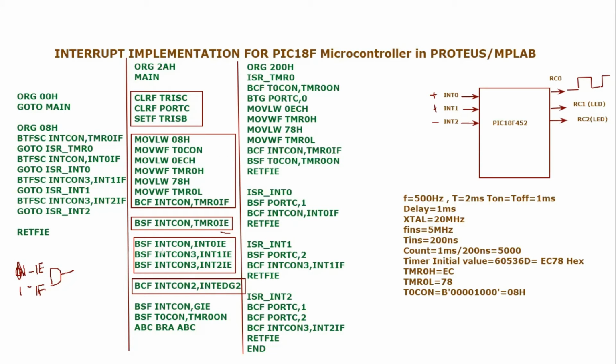And then we know that this is another important instruction for the interrupt mechanism. Though there are individual gates, they finally arrive at the main output of the interrupt, and that main output is again ANDed with another input. If you don't make that input 1, your interrupt won't go to the microcontroller, and that is GIE, right?